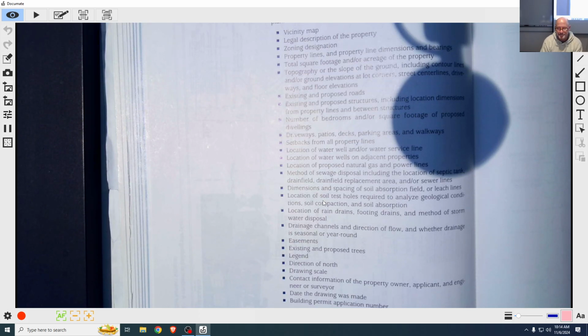North arrow, scale, the basic stuff that we've done on the project. Usually this stuff's in the title block. Other stuff in a legend, and there should be a notes section that explains something. All right, so that's your basics of what can go in. Not everything is necessary. Not all site plans will have all of this for whatever reason.